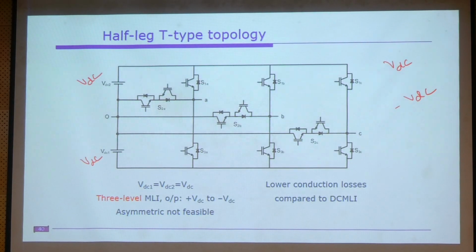You know that the firing pulse is connected between the gate and the emitter, right? If you use a common collector configuration, the collectors are connected together, so you need 2 gate driver circuits. With the common emitter configuration, 1 gate driver circuit is sufficient.